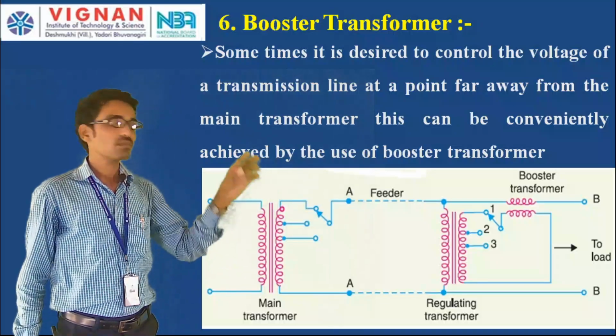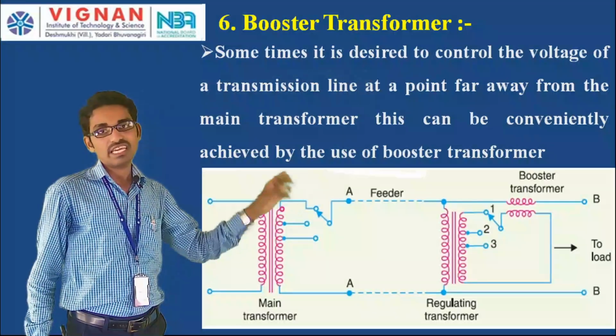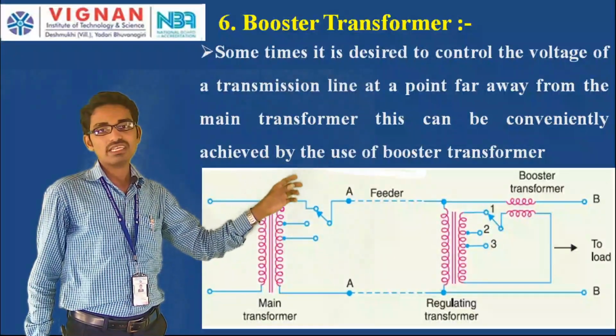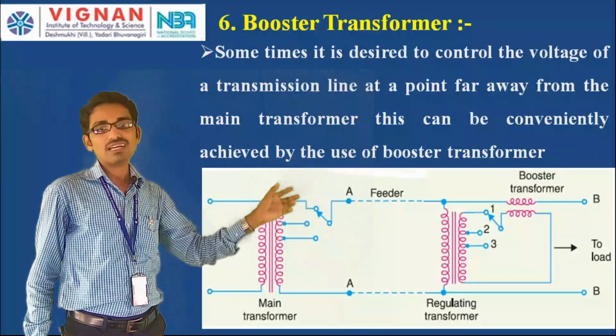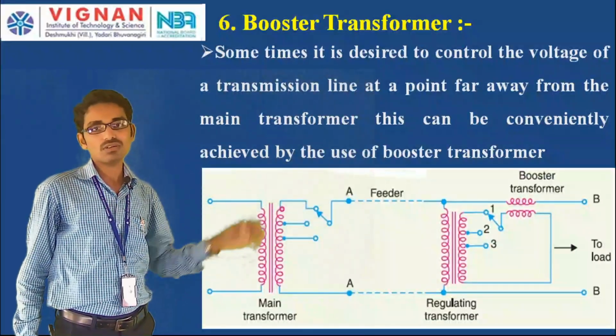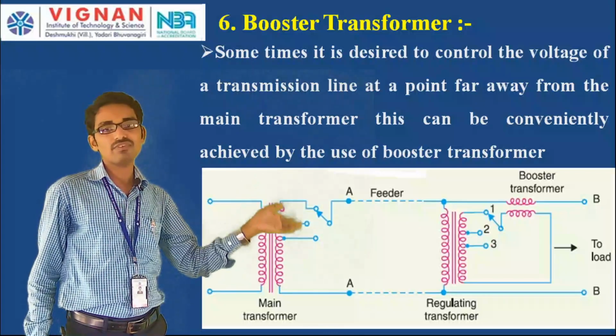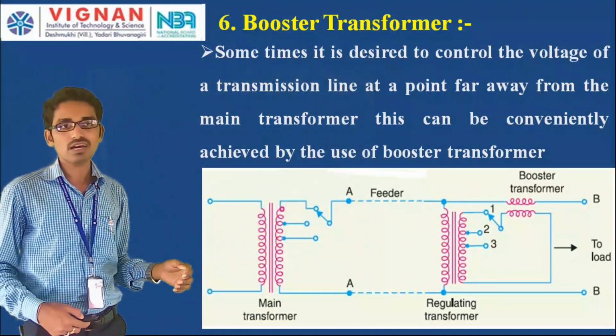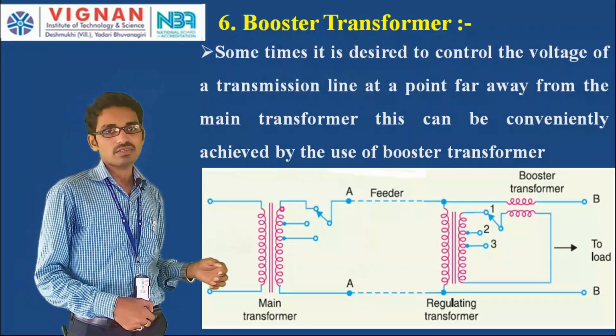This booster transformer will inject the voltage into the line. So then what happens is that the injected voltage is in phase with the load voltage. Whatever voltage is there, that is in phase with the voltage. Right. So that is what your booster transformer is.